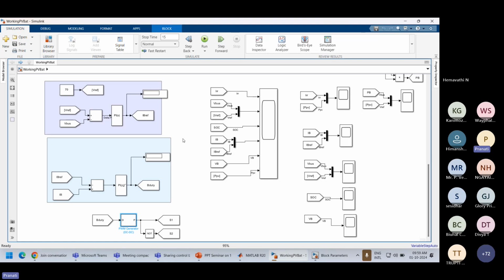Okay, ma'am. ITAE, have you heard of ITAE? Different indexes are used: ISE, ITAE. IAE, ISE is integral square error, ITAE is integral time absolute error. These all are the parameters used, and when these parameters are minimized, at that point, whatever KP and KI values the PSO algorithm gives is the final one.